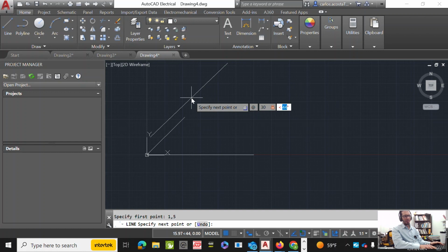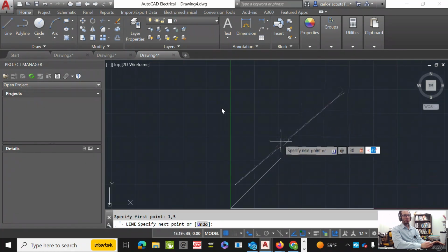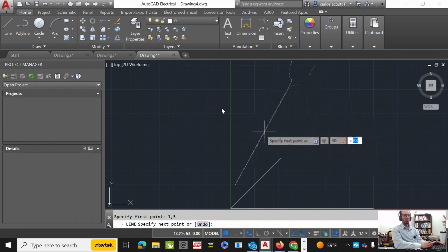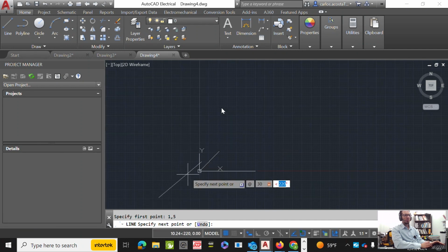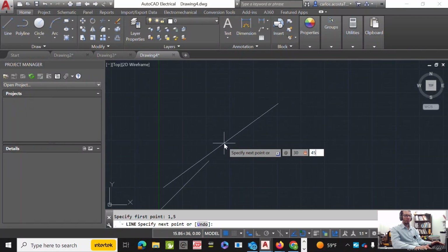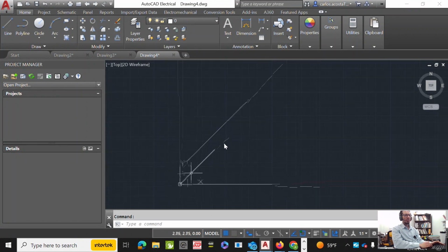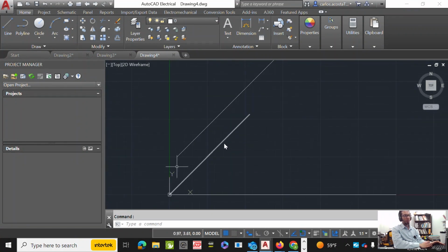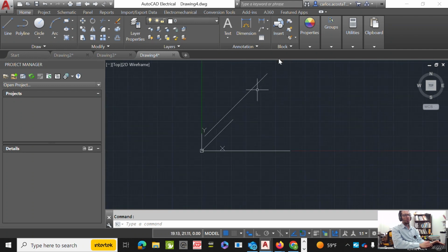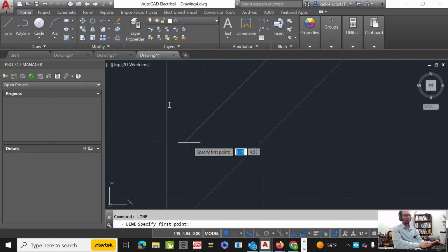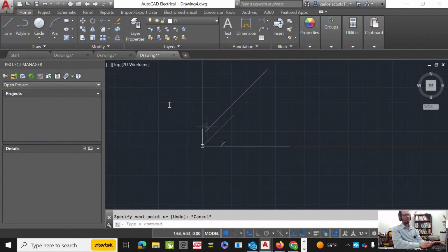If you type the less than, shift, if you go to your keyboard and you type less than, remember that's the angle nomenclature in AutoCAD. So it's waiting for an angle. So right now it's a 45, 50, 160, etc. 250, right? So let's say 45. Alright, enter. So now this line is at the first coordinate point that I chose, which is not 0, 0 anymore, it could be anything, and it's 30 inches long with an angle with respect to my x-axis. Actually, the x-axis is right here for the line, right? This is the x-axis for the line. So that is 45 degrees.